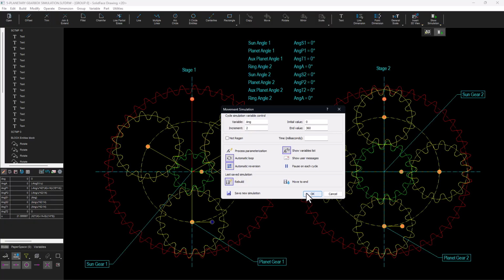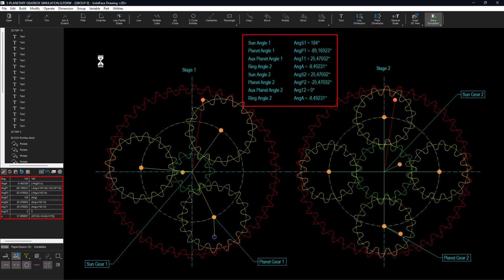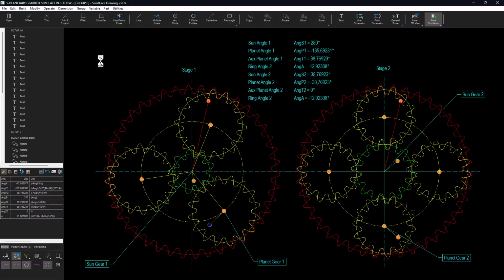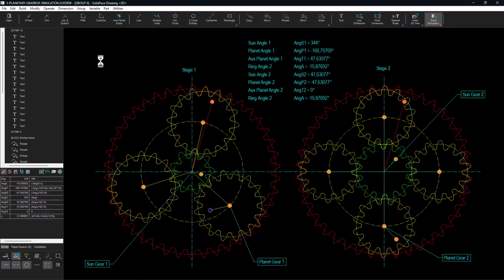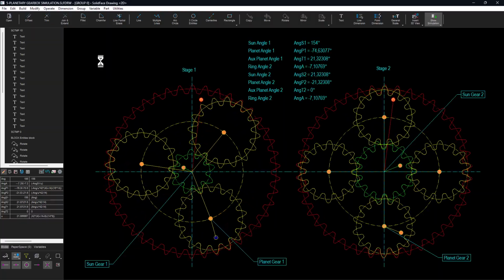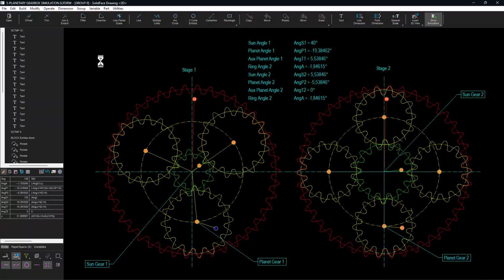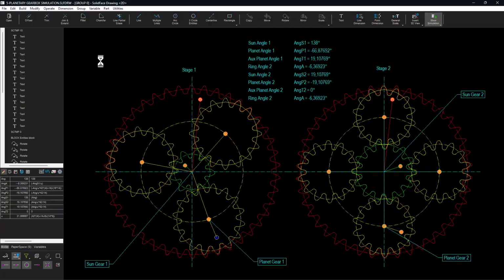During the simulation, the list of variables is also shown on the graphic screen. The central gear, called the first stage sun gear, rotates and moves the planetary gears around it. These gears transfer the movement to the annular gear in the second stage, causing the modification of torque, speed, and direction of rotation. This system is used in several mechanical devices.